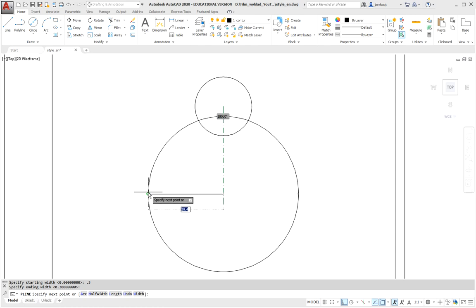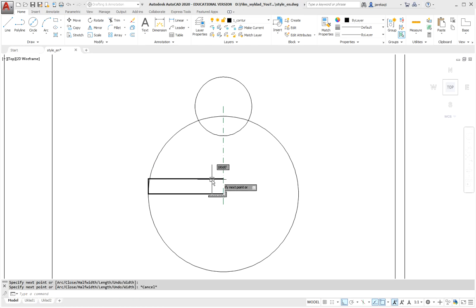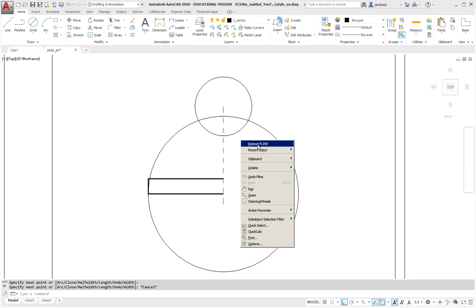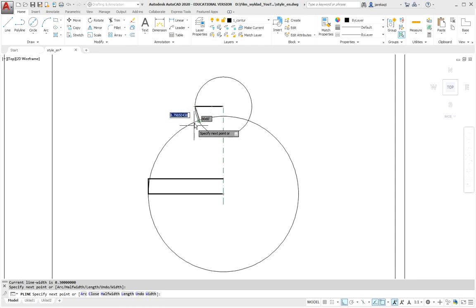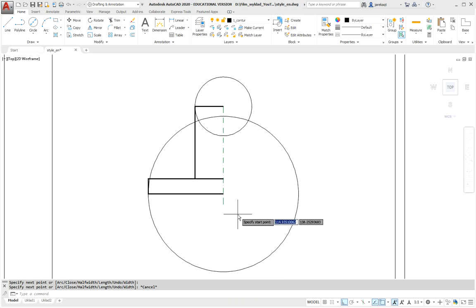And now there was a circle, 2 point, now to the quadrant of that circle. We're leaving up with ortho enabled 7.7, and to perpendicularity. In turn, we repeat polyline. We say from the end to the quadrant, and that was what the circle was for, and to perpendicularity. At the bottom we will start with the right key again, and from the end we go 10 left.